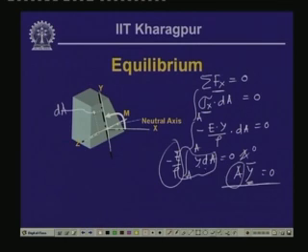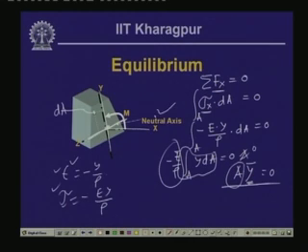And also, if y is equal to 0, then from the expression of strain, which we had as minus y by rho, and sigma as minus E y by rho, both the strain and the stress are 0 when y equals 0. That means at this particular point the strain and the stress are 0, and that is the reason this particular axis is termed the neutral axis.